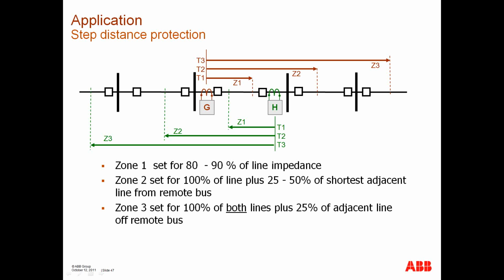Somebody asked a question. Let me pause a little bit. I have jet lag or some kind of lag here between looking at these messages, but somebody asked the question as to what comparators ABB relays use: cross-polarized, memory polarized, or positive sequence polarized. Well, we use a combination, actually all of them. In some cases we have positive sequence.